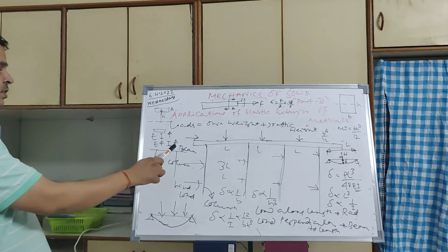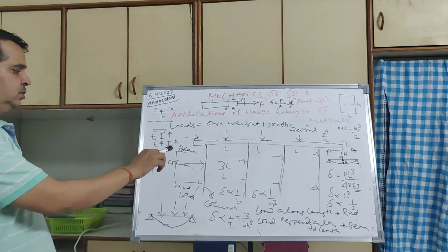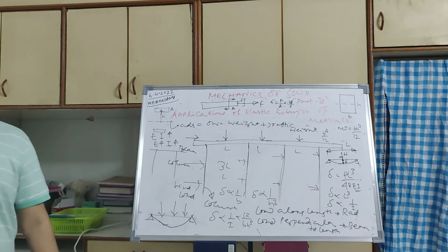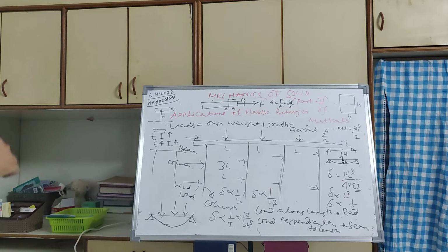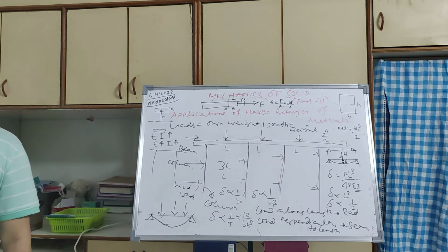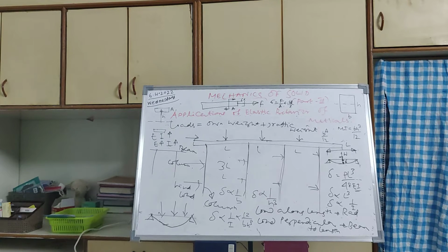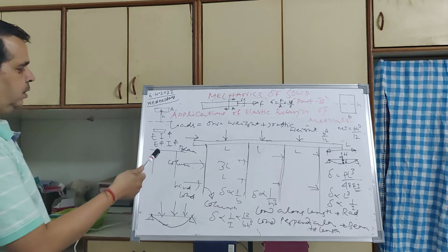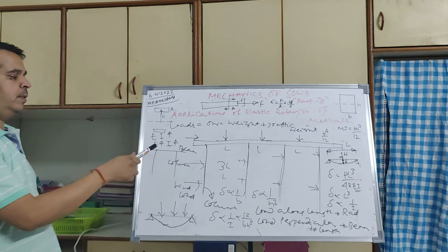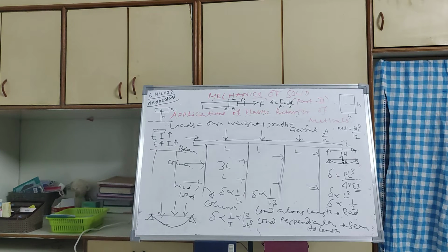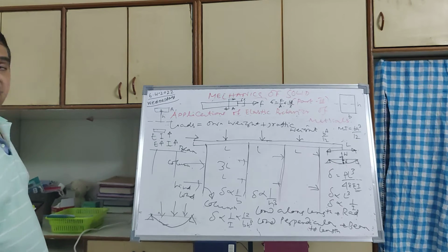So there is a roof on the building. The total load includes the self weight, the weight of the higher stories above it, and also the number of people it is going to carry. There will be some kind of load for which the building will be designed. That particular load will be transferred by the beam to the columns. Then we were discussing that these columns are made of concrete, so these columns will be taking compressive load.